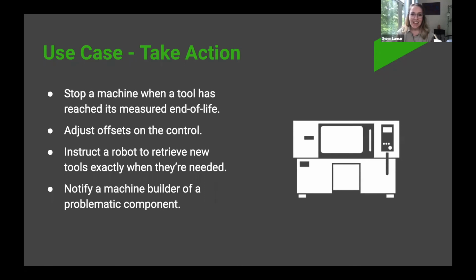Okay. Can the edge devices handle older data formats such as RS-232? Yes. So right now, I think one device that we connect to specifically over RS-232 is Haas machines. They speak a very specific protocol over RS-232. You can take another approach, though. We support a number of widely supported formats, protocols like EtherNet/IP, Modbus TCP, OPC UA. So you can add a second layer in between, translate some piece of equipment that we're not familiar with into one of these more open, slightly more modern protocols. Modbus TCP is actually pretty old. And translate that so that we can consume it.